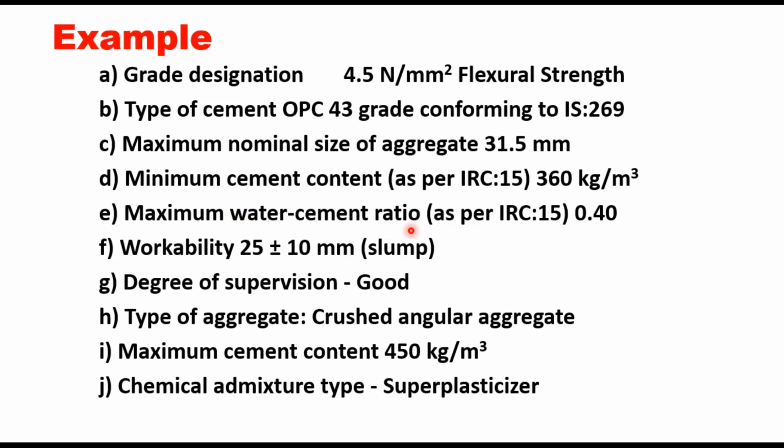Maximum water cement ratio should be limited to 0.4. Workability is desired as 25 plus minus 10 millimeter. Degree of supervision will be good. Type of aggregate, crushed angular aggregate, and chemical admixture type is superplasticizer.